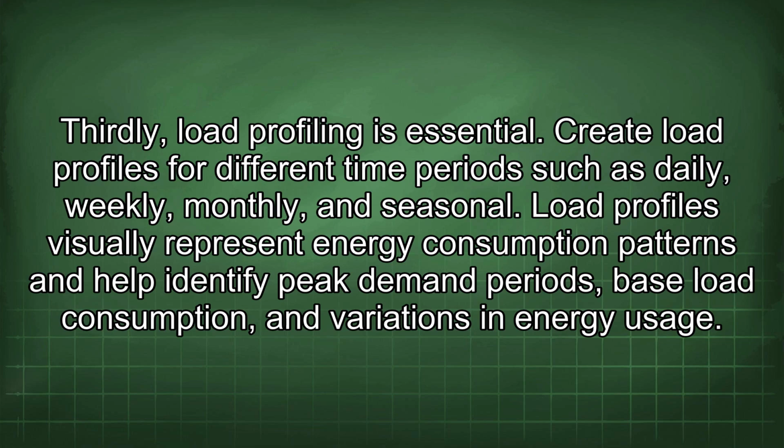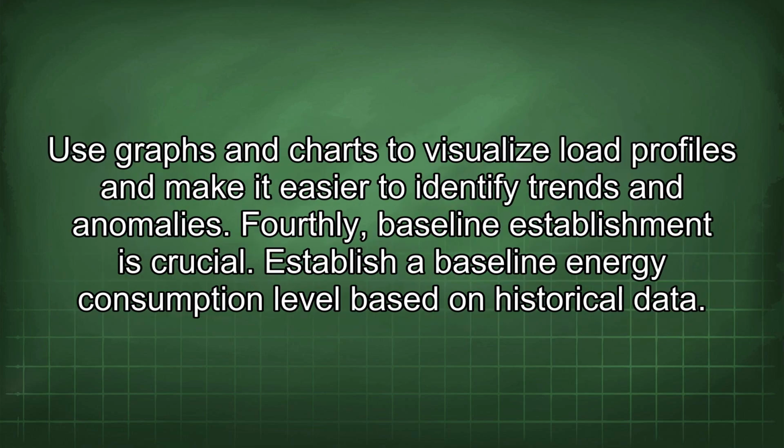Thirdly, load profiling is essential. Create load profiles for different time periods such as daily, weekly, monthly, and seasonal. Load profiles visually represent energy consumption patterns and help identify peak demand periods, base load consumption, and variations in energy usage. Use graphs and charts to visualize load profiles and make it easier to identify trends and anomalies.